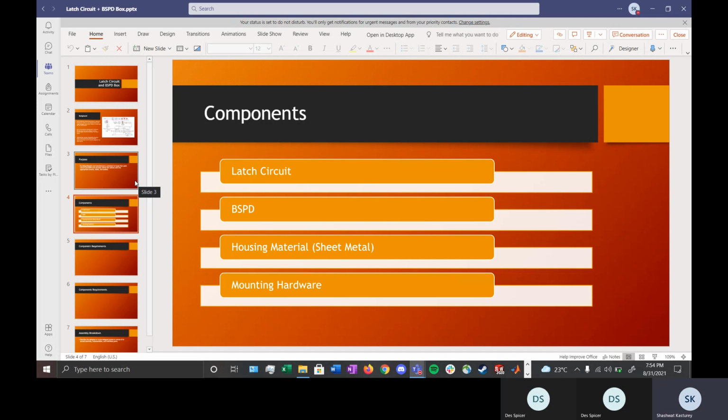What that circuit basically does is make sure you can't depress the brake and accelerator at the same time, and also make sure the compared signals at the accelerator match. The accelerator sensor of the car is actually two sensors in one housing, one at 3.3 volts, the other at 5 volts. If they don't match, something's pretty wrong, right? So this comparator circuit, this BSPD, shuts down the car. That's it.